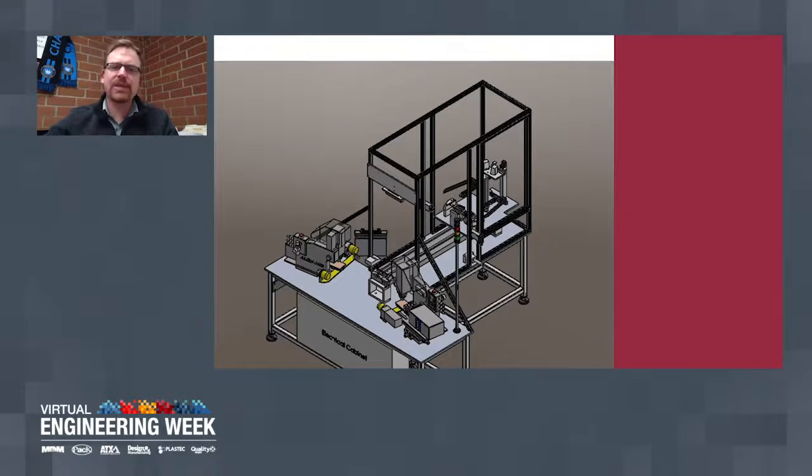These are right angle machines, so they're printing from the side, horizontal printers. So we're printing the left side and the right side of the part simultaneously. As they come in, they're passing through a pre-treat station to get that polypropylene to the right dyne level. And then it comes back, that robot's been waiting, pulls the part out, and it's ready to go on to pack out. So these are just some of the general fundamentals of automation with pad printing.